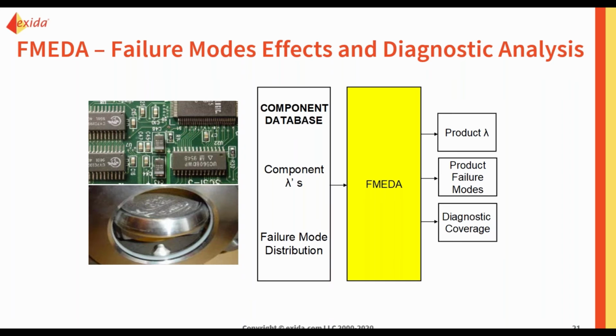Looking at the application, the environment, how it's going to be used, and seeing if it fails, if that could be a safe failure or a dangerous failure. The FMEDA technique is based off of the FMEA technique, but added in the components of diagnostics to be available. At the end of the FMEDA, you are presented with a product failure rate in that safe detected, safe undetected, dangerous detected, dangerous undetected, a product failure mode, diagnostic coverage, and even useful life for the device.